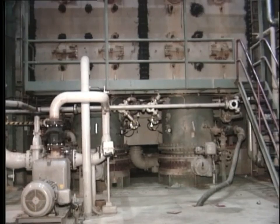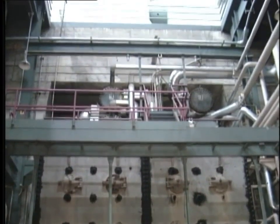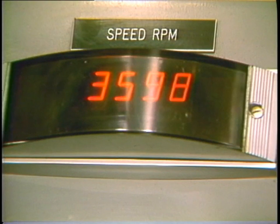However, if the turbine is of the condensing type, and this is far more common, then the steam exiting from the turbine will be at a pressure far below atmospheric, say 1 psia, and at a temperature of about 100 degrees Fahrenheit. Clearly, the amount of energy in the steam exhausted from the turbine is much less than in the steam entering the turbine. The heat energy has been used to force the turbine rotor to rotate at high speed and consequently produce mechanical energy. But how does it do this?